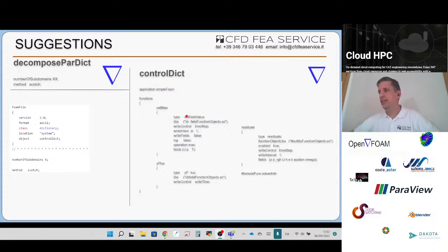After you have generated a mesh, it is possible to execute the CFD analysis using OpenFOAM. Obviously, you need to integrate the mesh itself with the missing information that is required for OpenFOAM.